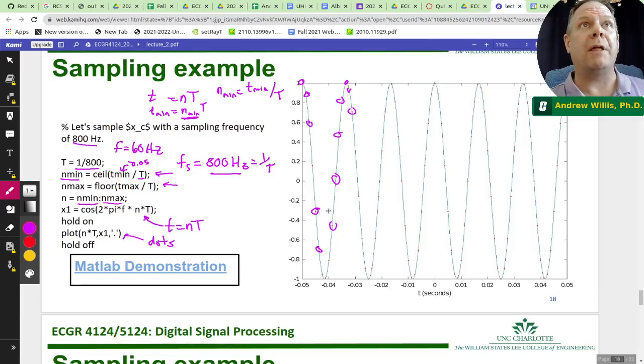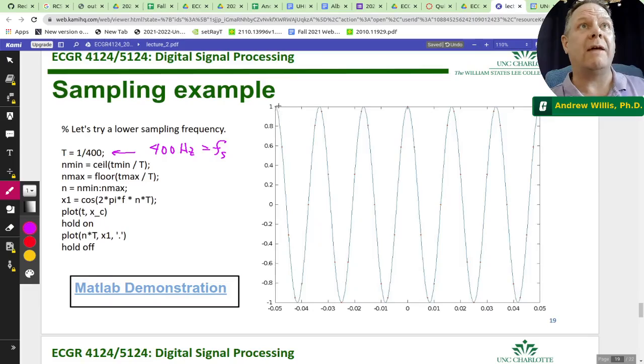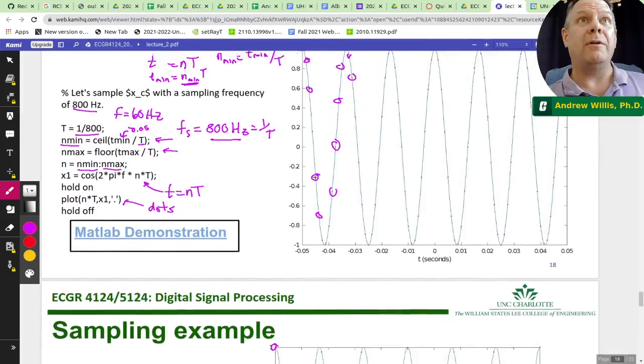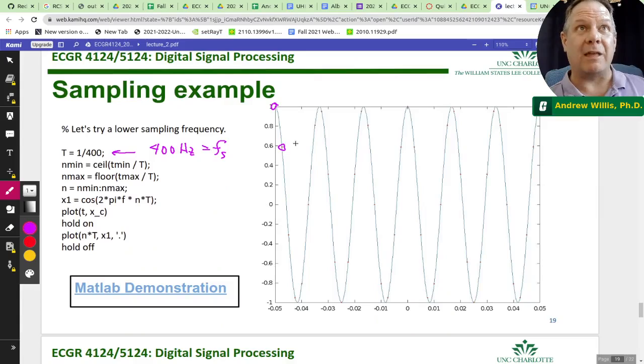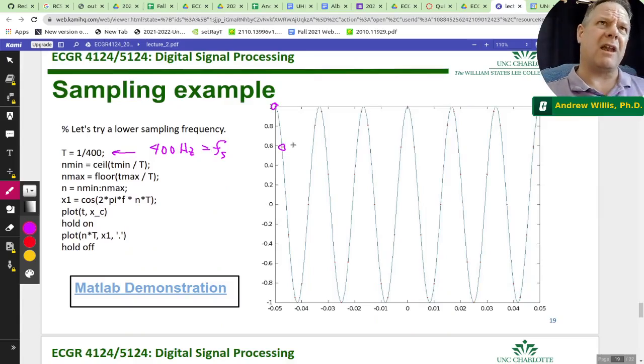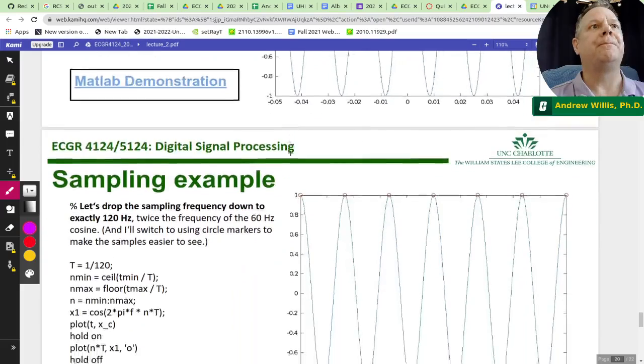But now when you sample at 1 over 400, you only have a sample here and here, and that intermediate sample was skipped. We are doubling the space between samples. So that means that every 2 samples from the signal above corresponds to a single increment from one sample to the next in this signal. It gives you an idea of how signal samples are related for different kinds of sampling rates.